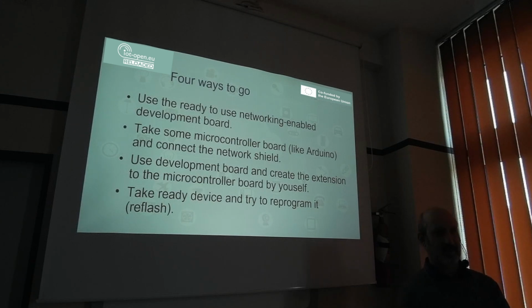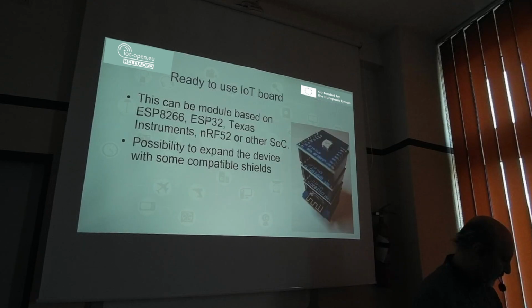And the last, sometimes it is possible to buy a ready device that has some functionality and try to reflash it. I know it needs some additional knowledge, but you are becoming engineers, so such a thing shouldn't be very complex for you. Just take the ready device, try to open it, but be careful about the power mains. And try to, for example, write your own program for this device. If it's based on a popular microcontroller or system on chip like ESP32, it is quite possible.